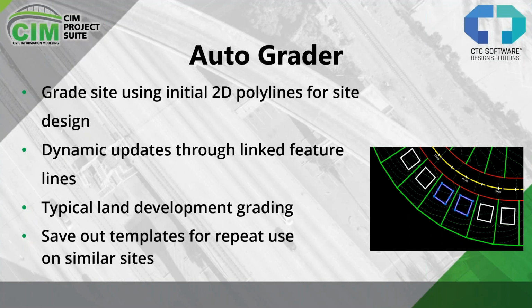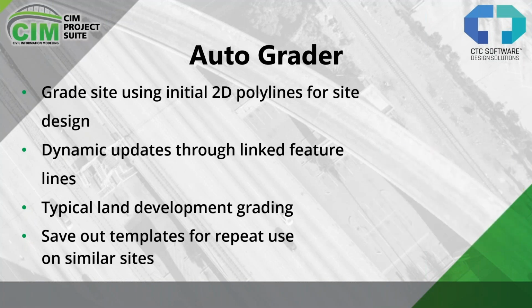And once you get that set up and into your drawing templates, hopefully you're using drawing templates, things are easily replicated. And like I said before, the break lines get created and they're dynamic to your surface. So they're linked lines, basically. And a lot of this is really handy for your typical land development grading. And like I said before, you can save out your templates to be used at sites where you're doing things over and over again.